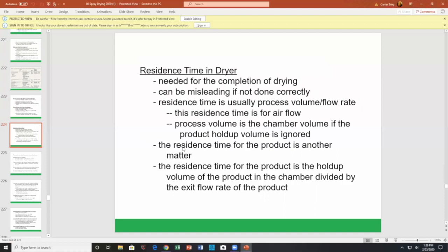Obviously, in spray dryers, that's not going to happen. Unless, of course, there's a side stream that trickles down the sidewall, from a plug or a hole in the feed pipe, or a misdirected nozzle, or one side of the wheel has substantially more liquid coming off of it than the other side, and I have a stream running down the wall. So all those are a violation of residence time.